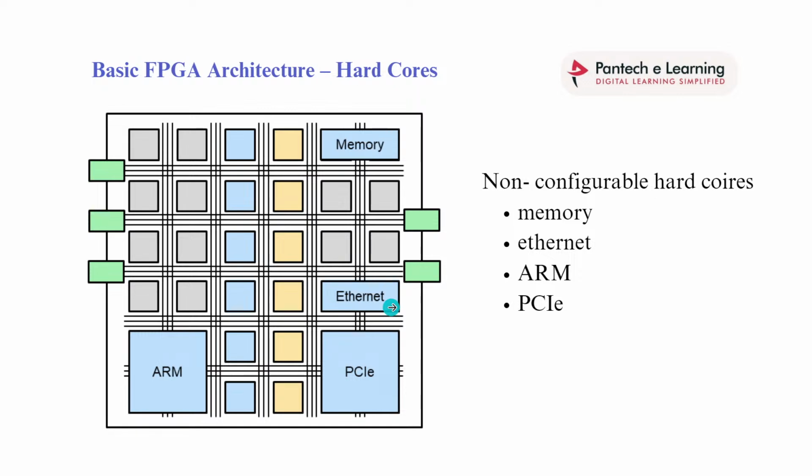And in the FPGA we can also transfer high speed data in gigabits also. By using the Ethernet, we can access up to 10 GB speed. But in a microcontroller we can't access this much high speed data transmission. In FPGA we can attain that high speed transmission. It is fully based on how we design the code, how we use the logical elements, how we assign the logical elements for each peripheral component like memory, Ethernet, PCI, and ARM.